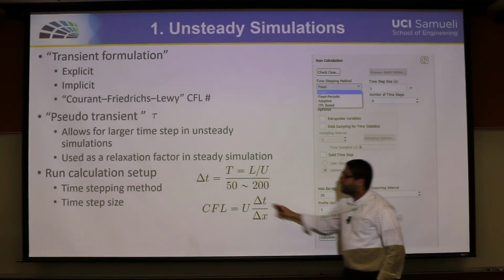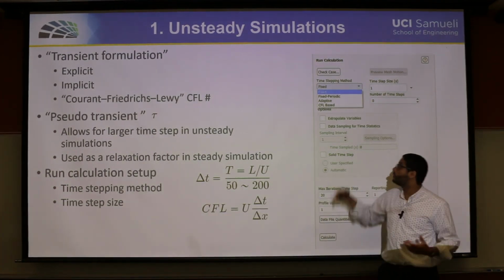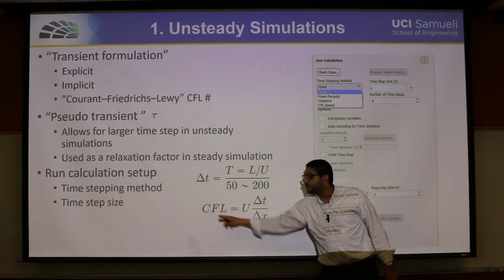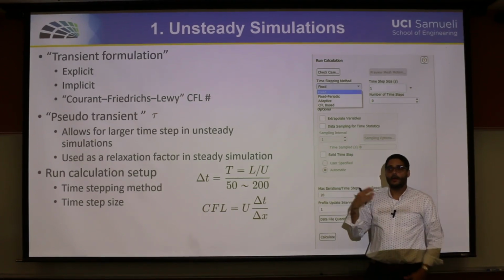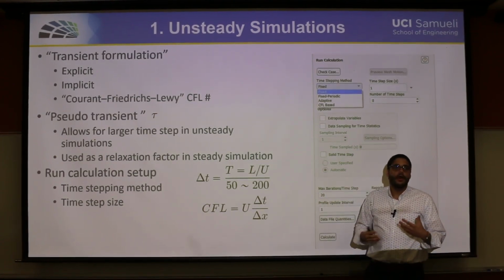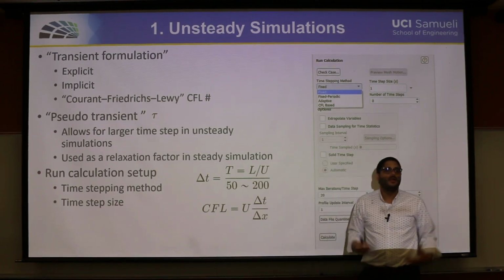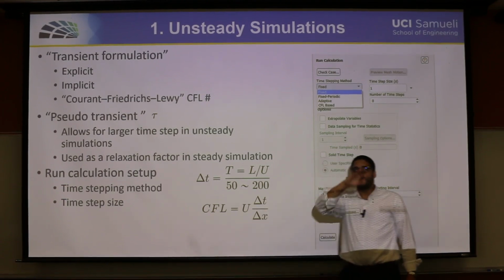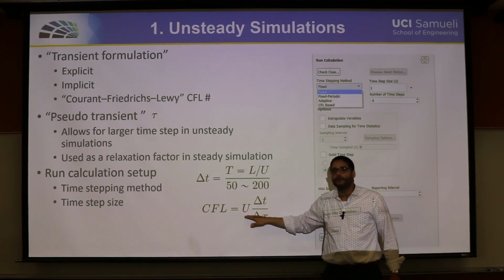And after you do all of that, at least make sure, if you're not going to use the CFL based, that your CFL is less than 1 in most of your domain. Okay, so the question comes on how I'm going to compute the CFL for each cell. You don't do that, but at least approximate the velocity in your domain. Maybe in the far stream, take it as just U infinity.